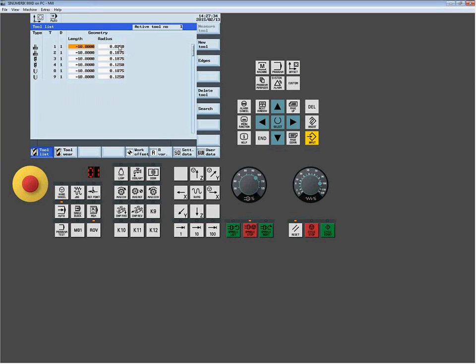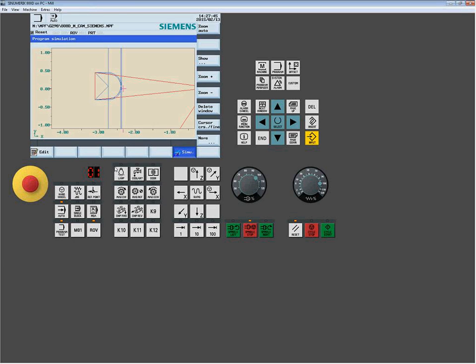They establish all of their tools at 0, and they'll put small incremental values here, plus or minus. Like if I was to set this value to a -25, I'm going to now see the exact same path, but now there'll be a new line on the right side here. So there's a new line on the right, just estimation. And that's certainly a valid scenario to run your machines, and now you still have adjustability if your parts aren't coming perfectly to size without having to repost the whole file.